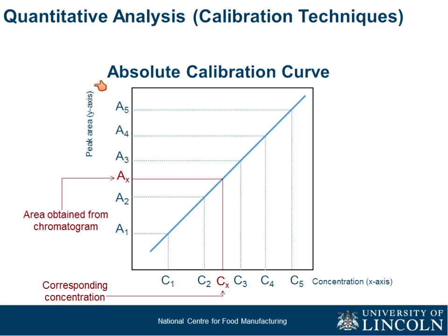If it's outside the scale, it is like saying I have the capacity of between 1 and 10, and you can't come and say you want to use me to measure 100. For example, if a pump is designed to inflate to a pressure of 1 to 10, and you want to inflate something to 100 psi, you need something for 100 psi. You can't use that pump for that. It's not going to work. So your calibration curve is very, very important. You need to understand that principle of what you are going to use your calibration curve for.